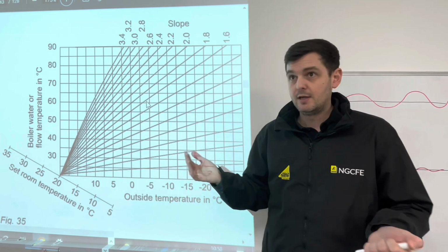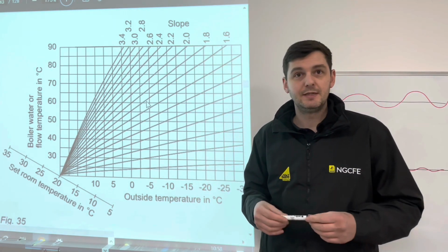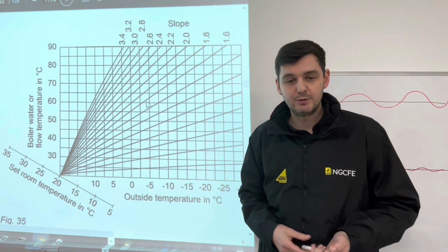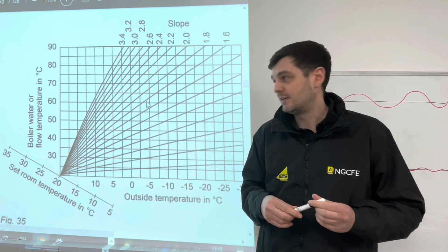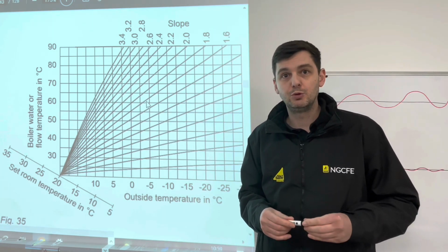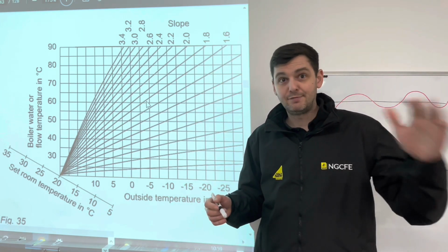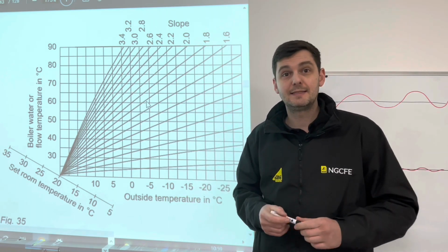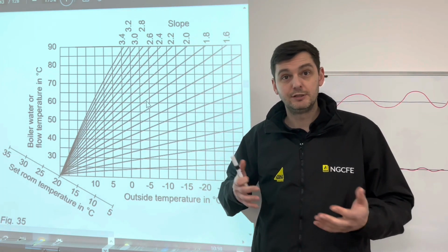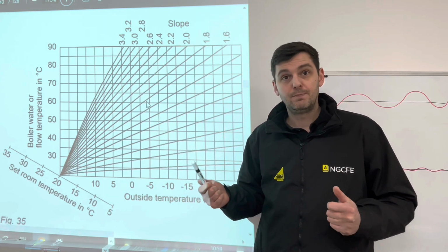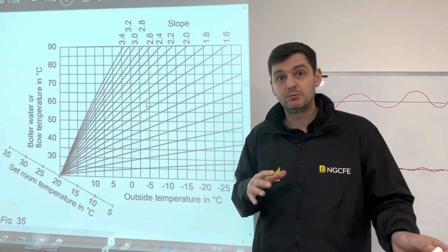The other issue with this, which people may find if they start using weather comp, is that this is relatively new technology to customers. So in the same way that we do have issues with heat pumps, customers generally might feel the radiators and say, well, hang on, my radiators are lukewarm or they're not that hot. I'm used to them being hot, especially if they've come from a traditional system where we've had high flow temperatures, on-off controls, where we overshoot and undershoot design temperatures. It's an education piece with your customer as part of, first of all, your design and your sale technique, and also when you're commissioning and you're handing the system over to the customer, you need to let them know this system isn't going to work the same way as your old system did.